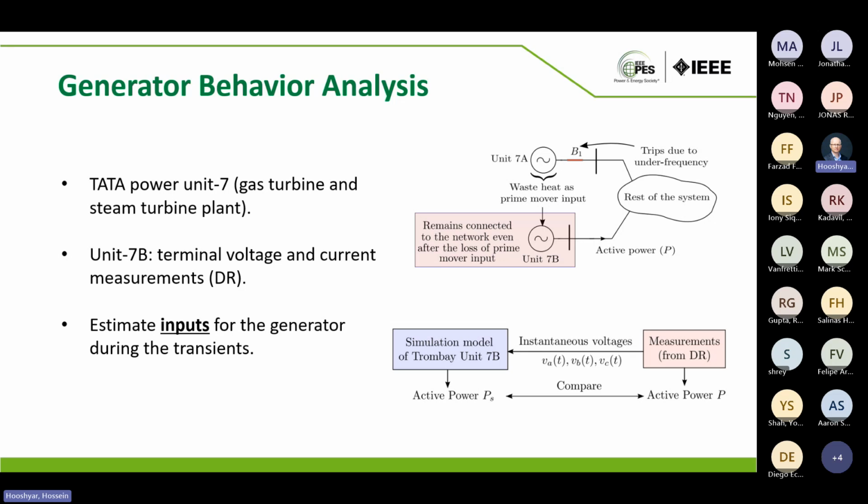So this is one of the possible challenges when doing an offline simulation, due to black box controllers or not always knowing the intricate details of the controllers. Although we sometimes have a fairly well detailed linear model of the controller, sometimes the non-linearities like dead bands and limiters are usually present but normally inactive. They are activated only under extreme situations. We may not always have the data very accurately for these components. And under such very rarely observed scenarios, it is very important to know the entire details in order to do accurate modeling and reconstruct the scenario in our simulation.